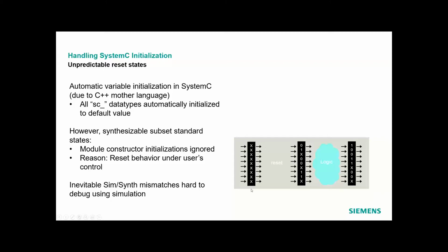That means if you have some register that is not initialized, these uninitialized values can propagate through the design and through the logic to the output, and your output can have some X values in the end.